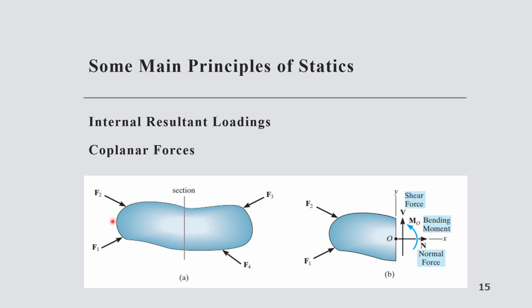Subjected to a coplanar system of forces. Coplanar, as I already mentioned, are the forces that act in only one plane. Then only normal force, bending moment, and shear force will exist in the section. If we use the xyz coordinates, then N can be obtained by applying